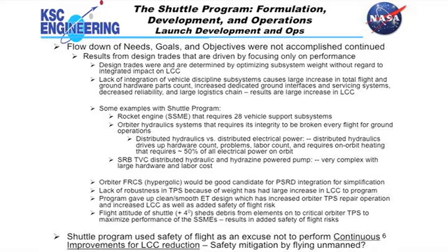And the hydraulic system, as we have it in shuttle, requires about 50% of the electrical power just to keep the fluid warm, so the system will be functional when you return to Earth. So again, another reason why to avoid distributed hydraulic systems.